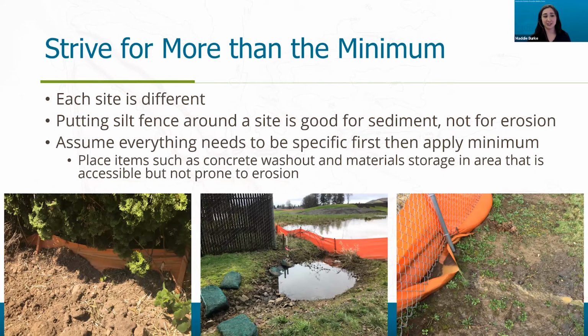I also want you to consider where you place items on the plans, such as concrete washout and material storage areas. You want it somewhere that's accessible. Concrete washout, you want it to be somewhere where the concrete truck drivers will see it and be able to wash out their chute. But you also want it somewhere that's not prone to erosion. So you don't want all the rainwater from your site going into your concrete washout area.